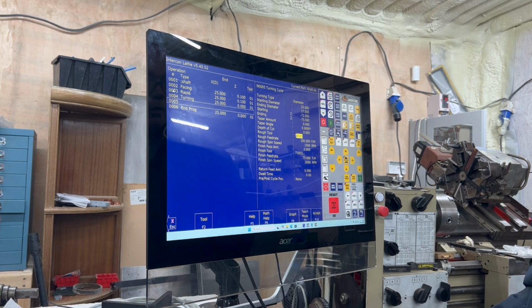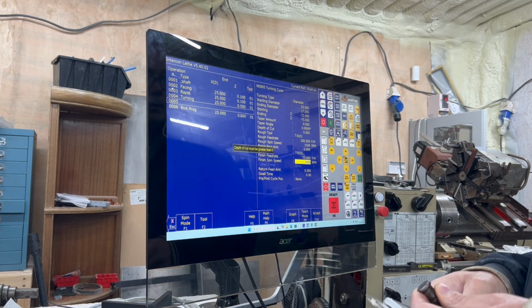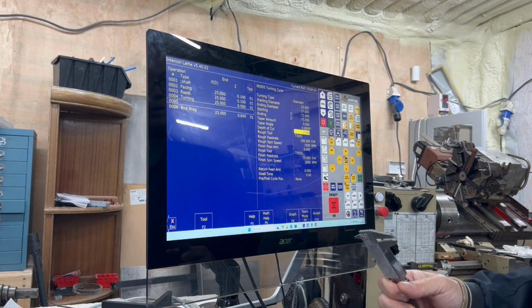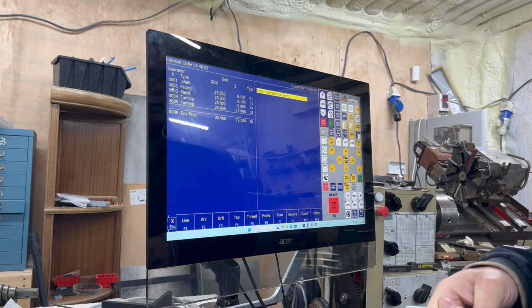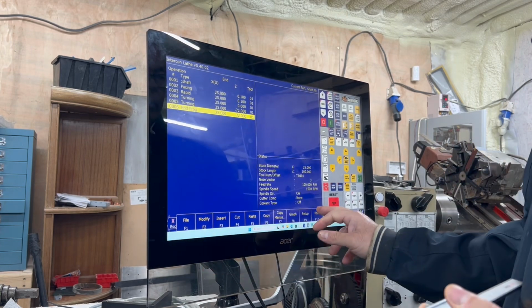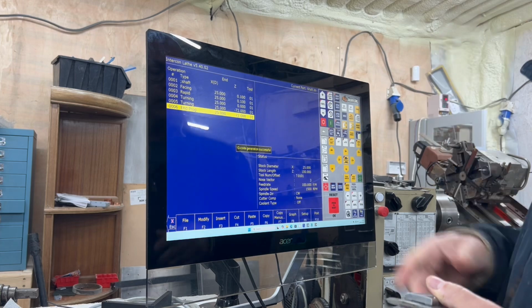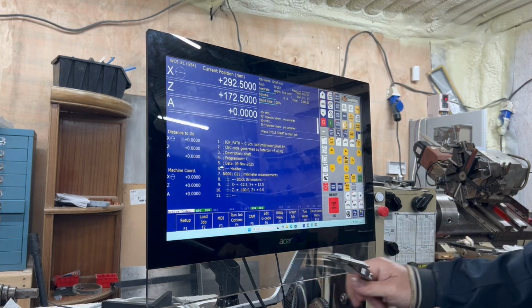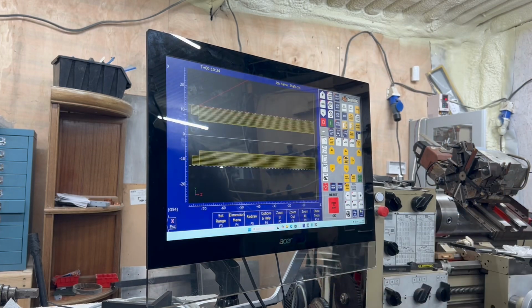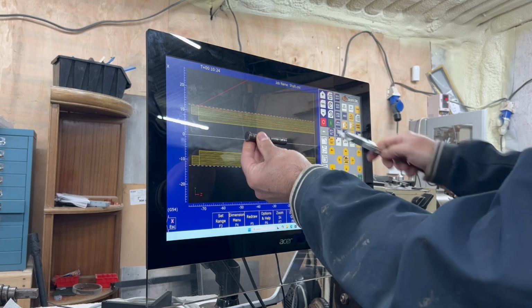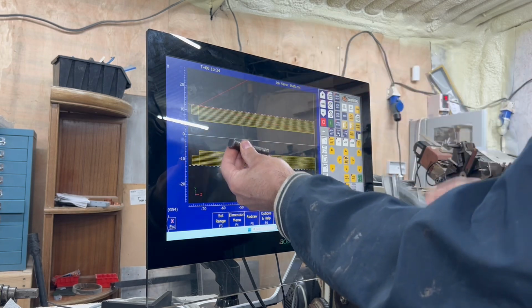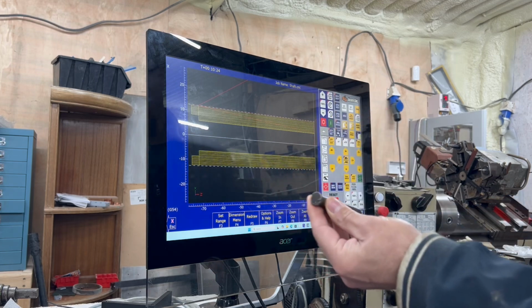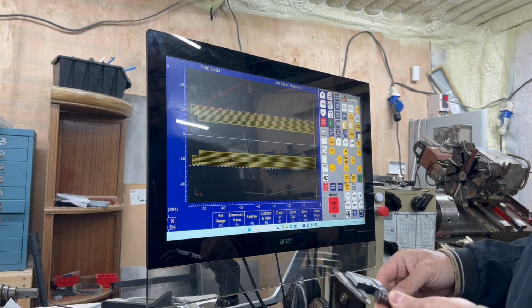No taper, roughing tool, I'm going to use exactly the same settings as before. Accept. Depth of cut must be better than that. So again 0.5, do that, accept. Go back, post. And if everything's right, we should now see a part that resembles this graph job. And there we have it. So you can see the shape there, the shape there, the shape there. And that is Conversational, easy done, quicker than doing it on CAM software.